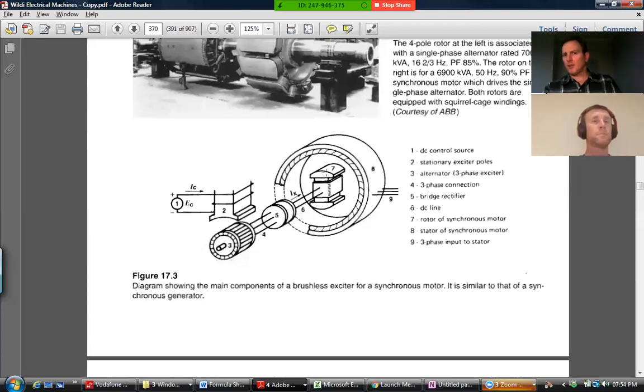Now, it doesn't need much current in theory, because if you make this quite a thin wire with 25 gazillion turns, you just need a couple of amps, because amp turns is the driving force that makes a magnetic flux. So if you have lots of turns, you can have a very small amount of amps. So you can have a relatively low amount of power drawn here from this little mini generator. Remember, because we could be getting this free if we tried hard enough.